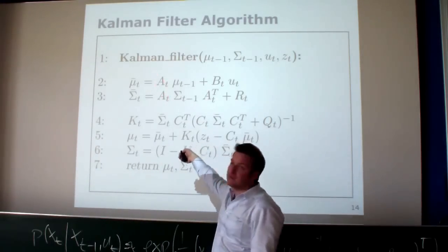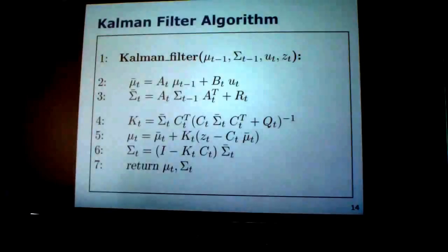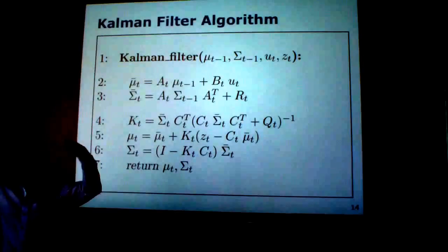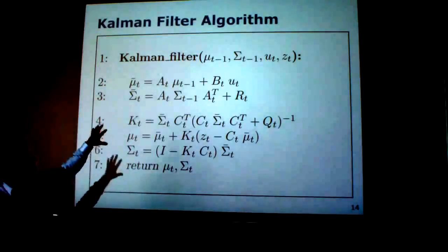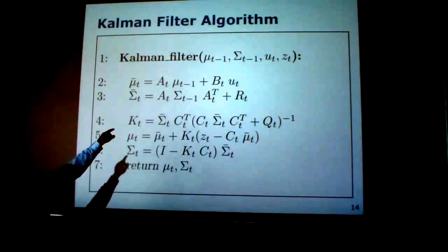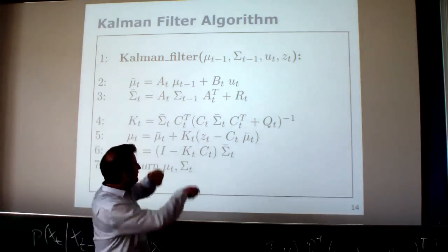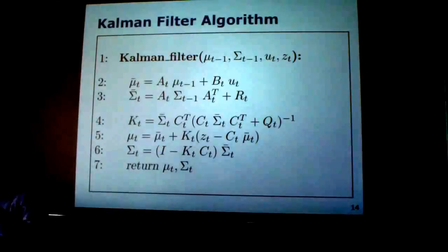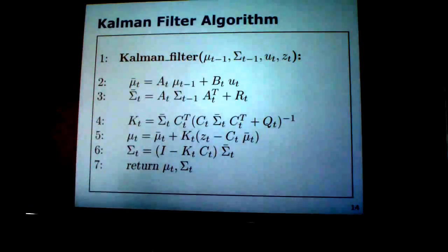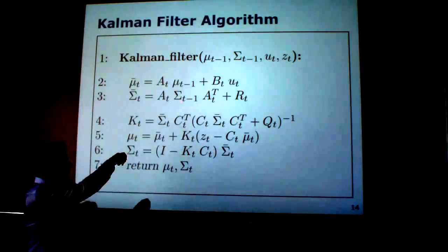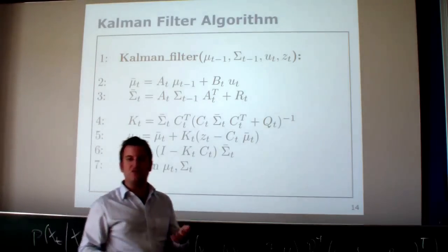And if A_t does some transformation, for example scales some weird system where the size of the space grows over time, then the uncertainties would grow accordingly. So depending on how not applying any motion changes my state, the covariance matrix needs to be transformed accordingly. And these equations result from how a Gaussian changes through a linear function with Gaussian noise. That's just what comes out of that. Again, if you want to go into the details, it's quite some derivation. My goal here is to give you an understanding of the individual quantities.